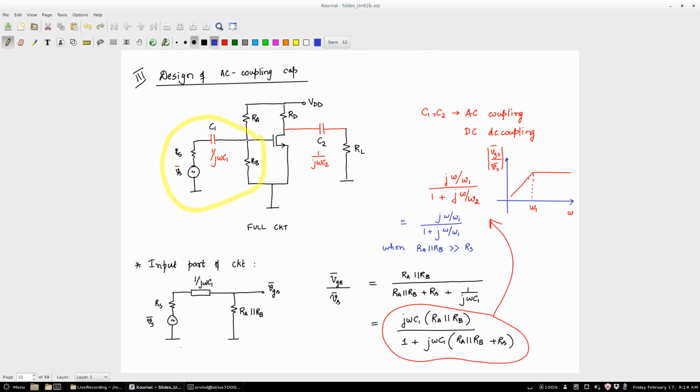But do you appreciate the fact that the analysis did not include the AC coupling capacitors or DC decoupling capacitors? So in the absence of including the effect of those capacitors, we just got a low pass response dominated by the dominant pole.